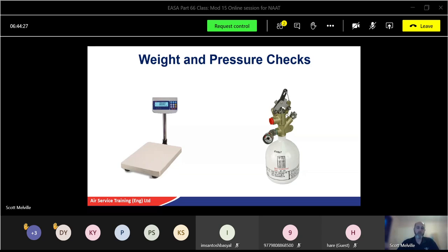Even standard fire extinguishers in buildings, they get weighed usually every year to make sure they're okay, even though it's never been used. So things like the date of the weighing and the weight should be specified, recorded on record cards or log cards as we call them, for each type of extinguisher, and also labels on the equipment. If the weight of the extinguisher is below that indicated value, it must be withdrawn for recharging. Okay, pretty much you'll take them out of the aircraft anyway and send it off to get checked. You probably won't weigh them unless you're authorised to do so.